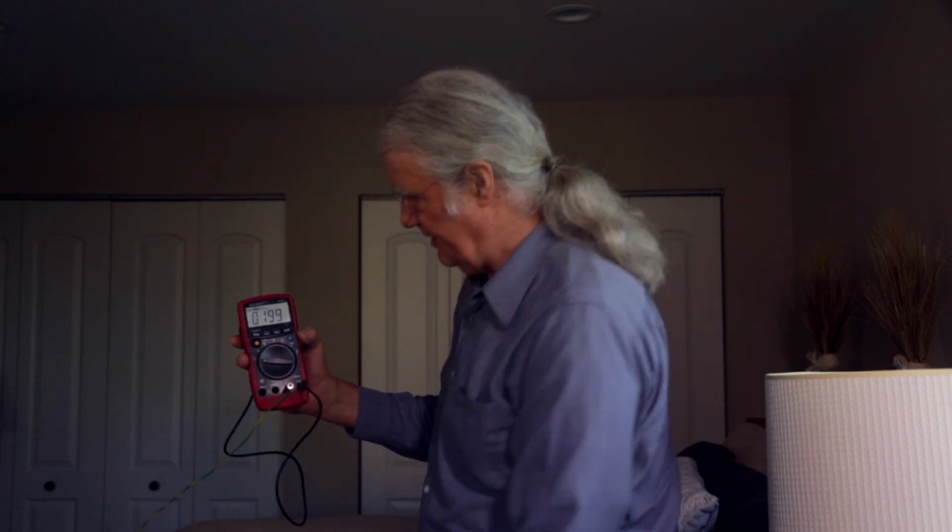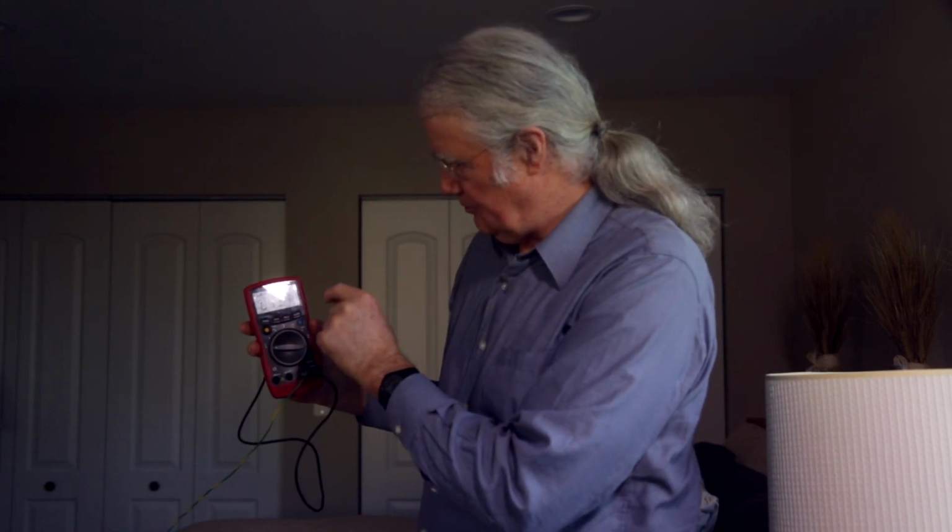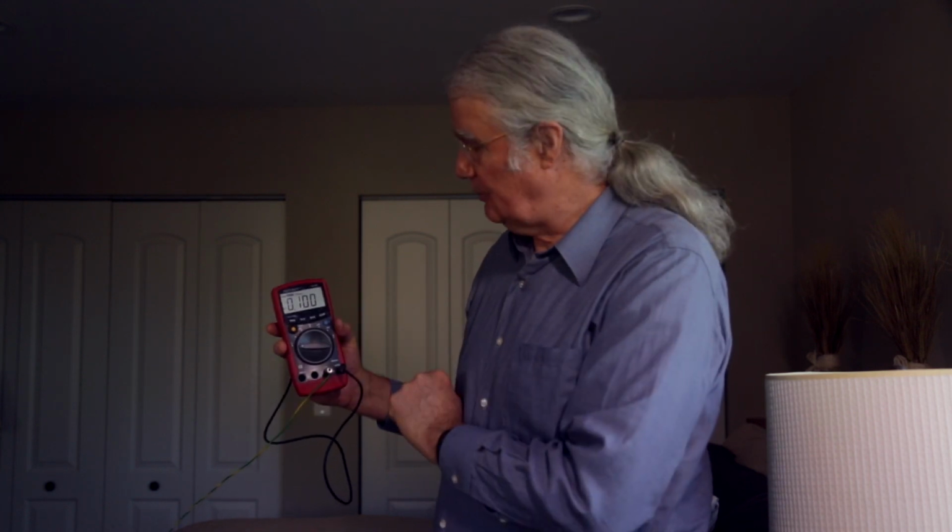Now that number is close to 100, 130, 140 millivolts or 0.13 volts. So we are now at what we would consider to be at least in the slight anomaly range. It's not always possible to get into the no anomaly range, which would be 10 millivolts or less, but at least we're in the slight anomaly range and out of the severe and extreme anomaly ranges. So we would consider this to be a safer sleeping environment than when we started, which was 2,000. So we've dropped this down 95%.